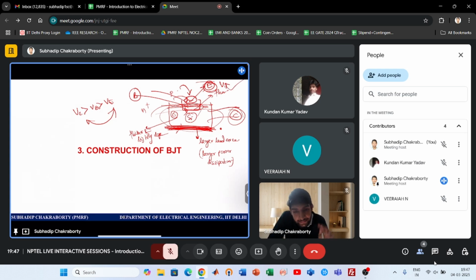In other words, if you do not damage it, then you have a lower voltage at the output, which will not amplify. The main purpose of the BJT, which is amplification, will be lost. Because now, in a larger zone, you are actually biasing it with a lower voltage, which will not lead to the transfer of the total number of carriers.